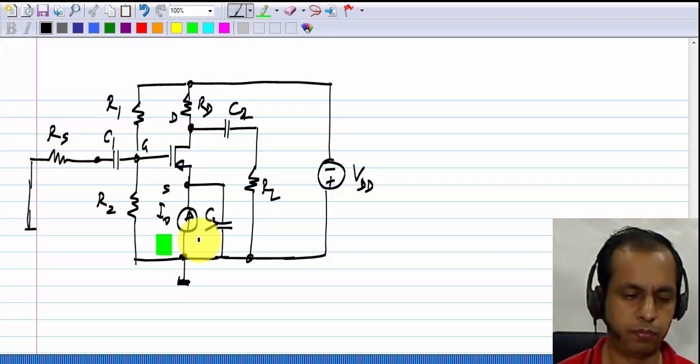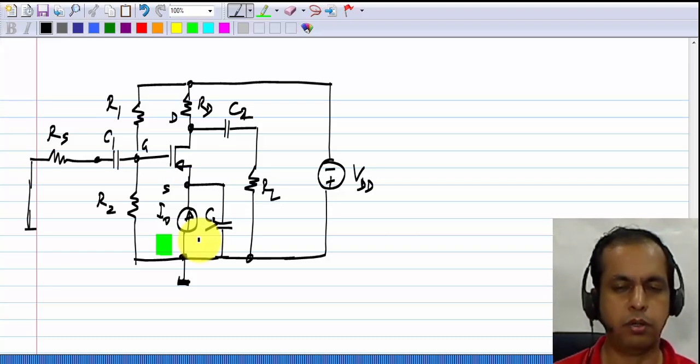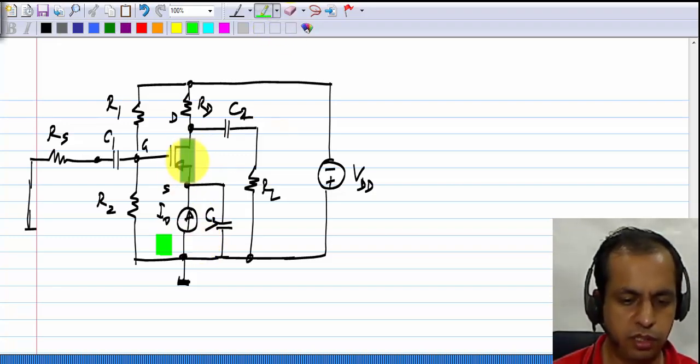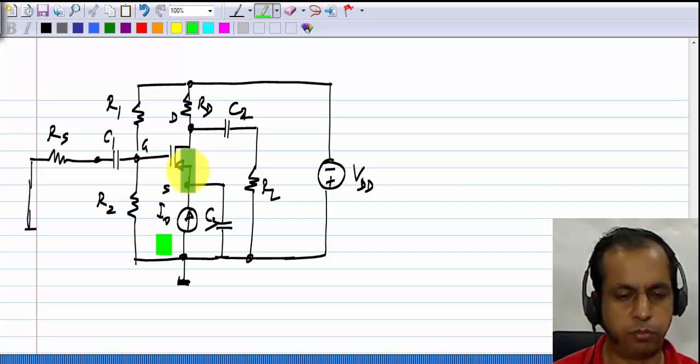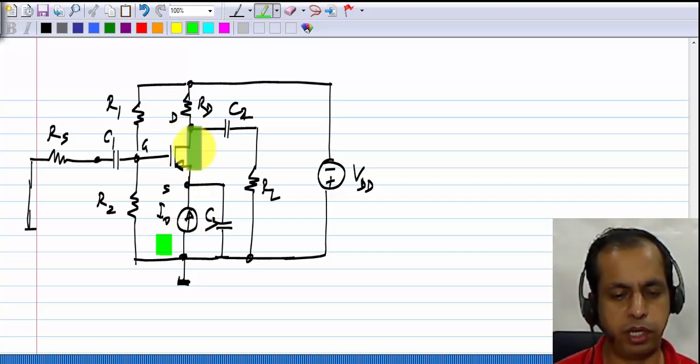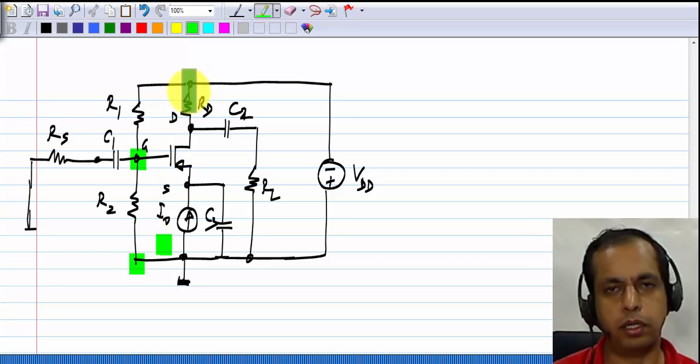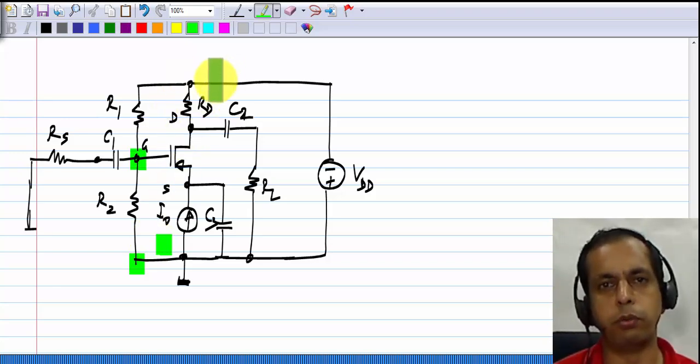So this is the operating point picture. Now, that's all there is to it. In this case, the current from source to drain of the PMOS transistor will be I0. Because we reversed the sign of VDD, the voltage between R1 and R2, and in fact between any two node voltages in the circuit, will be exactly the negative of what we had before.